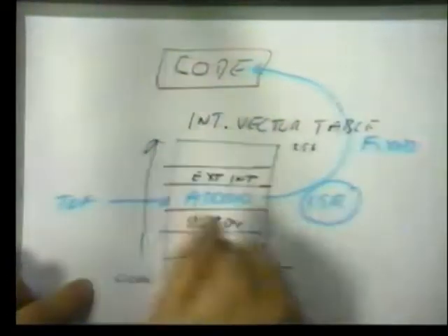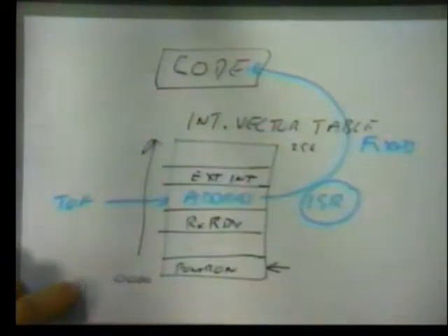And most modern compilers for microcontrollers actually automate this process for you. As long as you create a label that marks the start of the interrupt service routine, and you state that that label exists in the memory block, it will generate the code for you. So a lot of this happens automatically. But that is the role of the vector table. It tells us where to go.